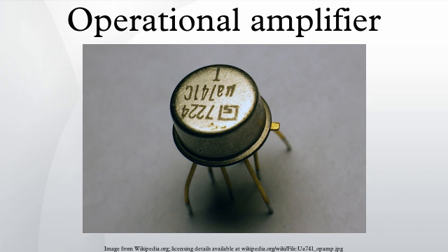Positive feedback applications. Another typical configuration of op-amps is with positive feedback, which takes a fraction of the output signal back to the non-inverting input. An important application of it is the comparator with hysteresis, the Schmitt trigger. Some circuits may use positive feedback and negative feedback around the same amplifier, for example triangle wave oscillators and active filters.